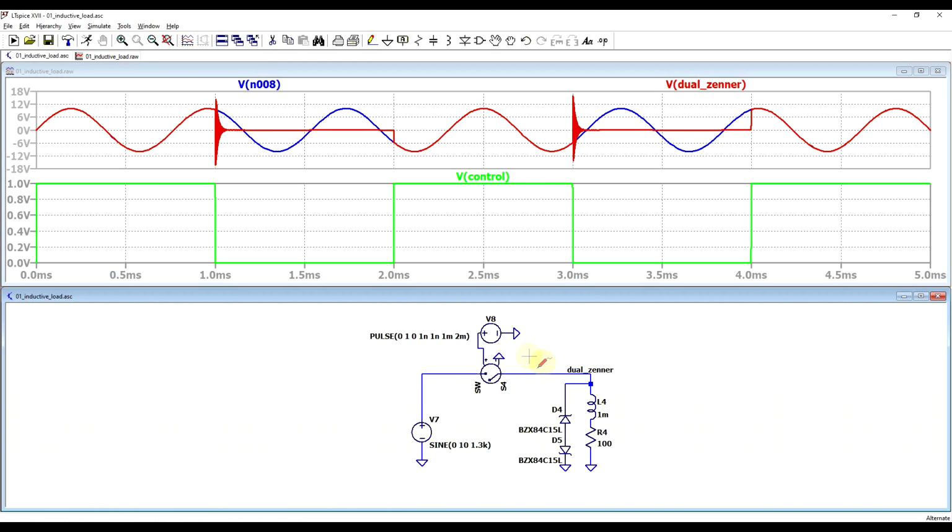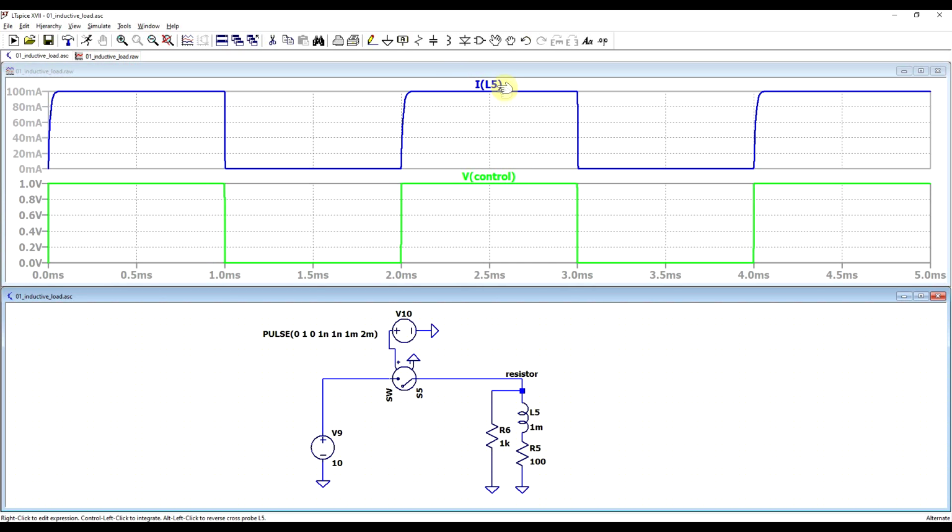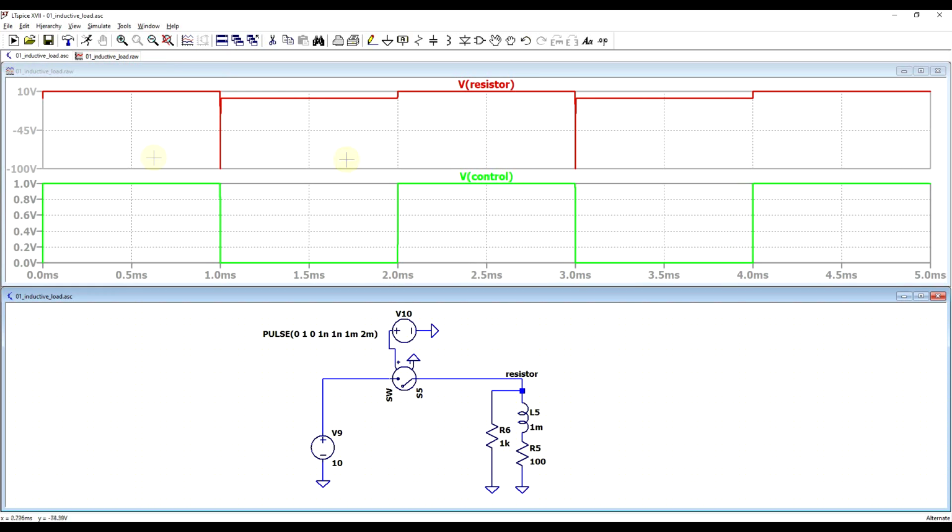Now, if you don't like semiconductors, you always have the option of using passives. And here, the most basic version involves using a permanent resistive load. So whatever current was running through the inductor needs to drop to zero, so in this case it's 100 milliamps. So if we add in a 1 kilo ohm load, the inverse voltage will be limited to 100 volts. So this will be the voltage that occurs when you pass the 100 milliamps through the 1 kilo ohm resistor. You can get smaller voltages, but then you need a larger permanent load. And well, you don't really want to have permanent loads added into your circuit.